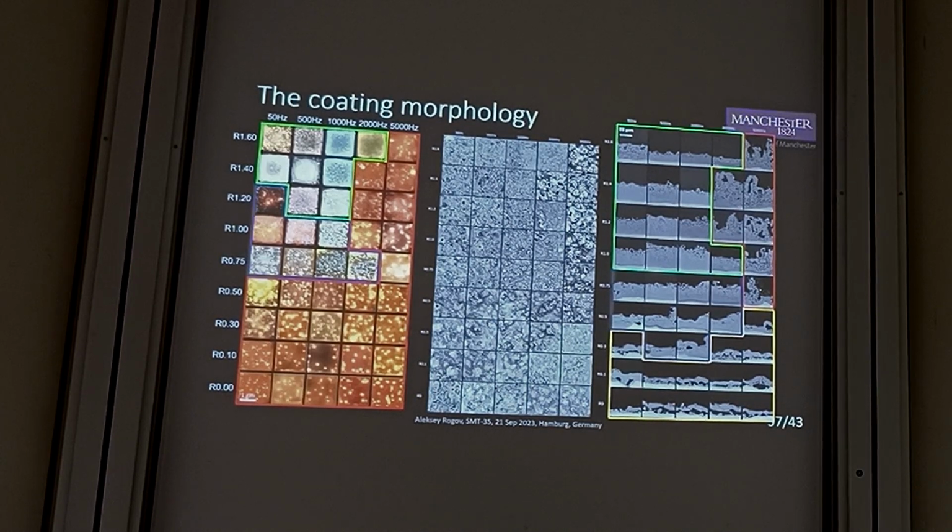So here you can see cross-section micrographs. What's interesting in regards to that microarcing region is that it demonstrates two types of morphology. The high frequency corner or region shows a columnar type of porosity, I would say. However, the low R factor, low frequency region shows a laminar, almost completely detached coating. In regards to the soft sparking, we can see very dense, flat coatings, where the oxide-metal interface is almost flat, in contrast to other regions. We'll have some intermediate features here.